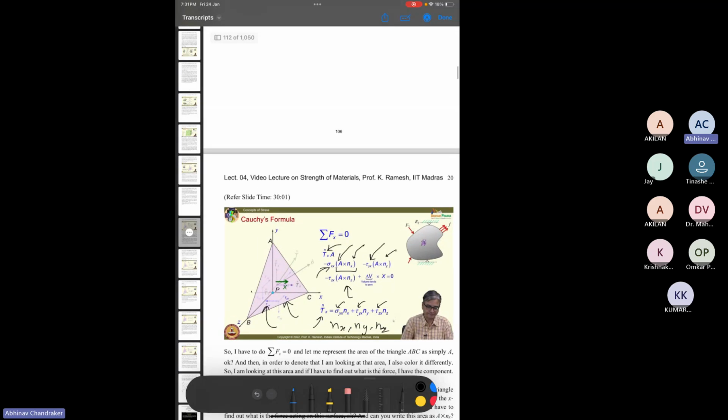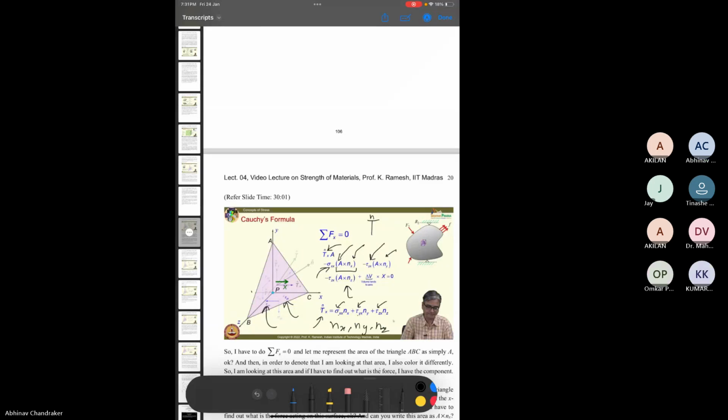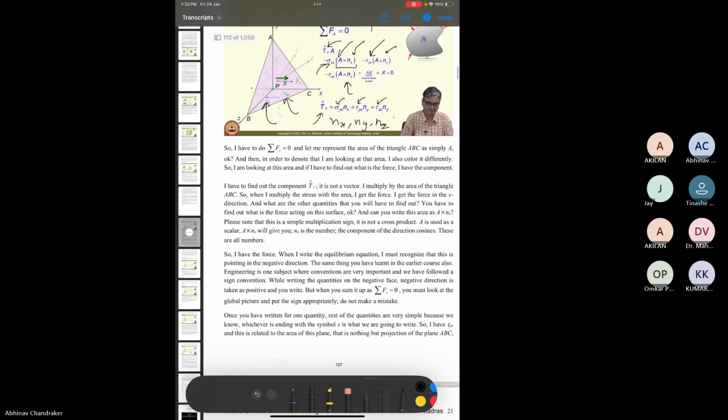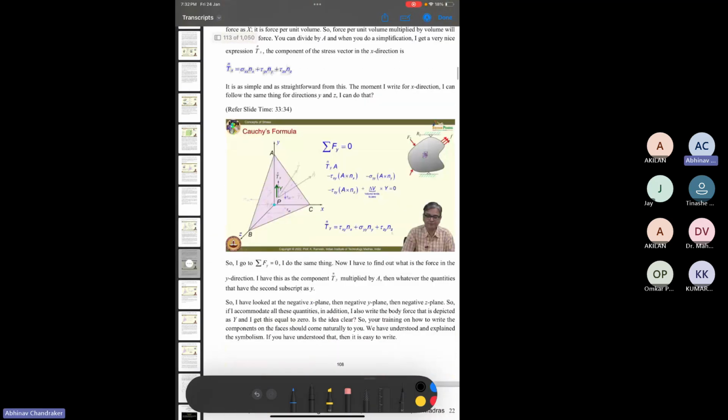So you can understand this as every point having a stress vector T, let's say Tn, for a particular plane, and this can be written as a function of the value of stress components which are invariant of the plane you have chosen. It will only depend on the coordinate system that you choose, and we want to represent it mathematically.